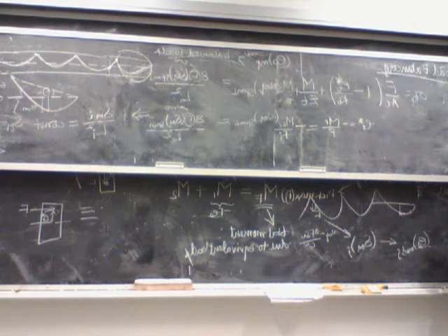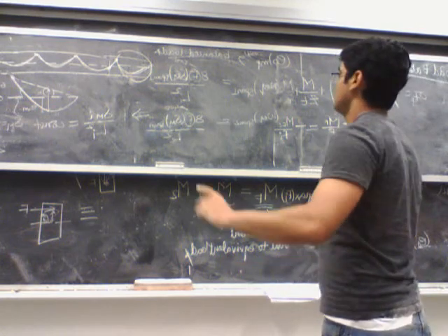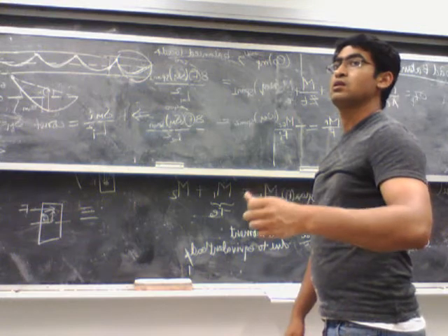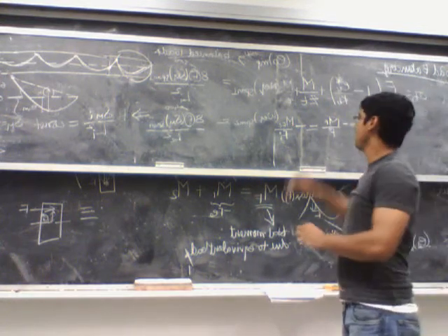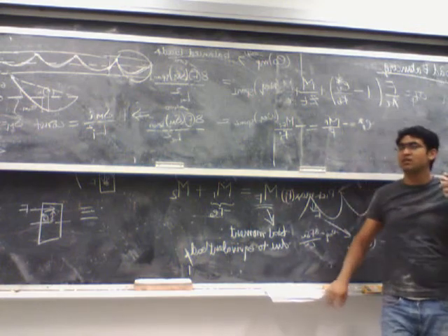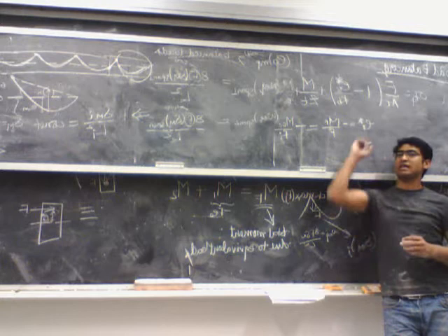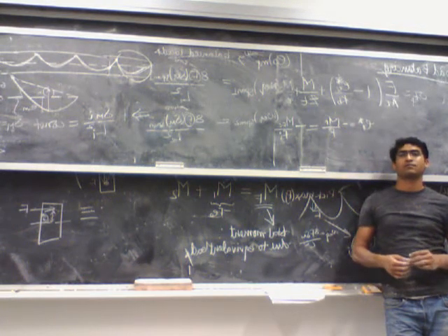Okay, so the M2 is in the M, right? So that would be like an MF, and then the M2 is in that M. So the way the M2 gets factored into your E star is that in the MF, because MF is the sum of that minus F E naught plus M2. So this MF already contains the effect of the secondary moments. Okay.